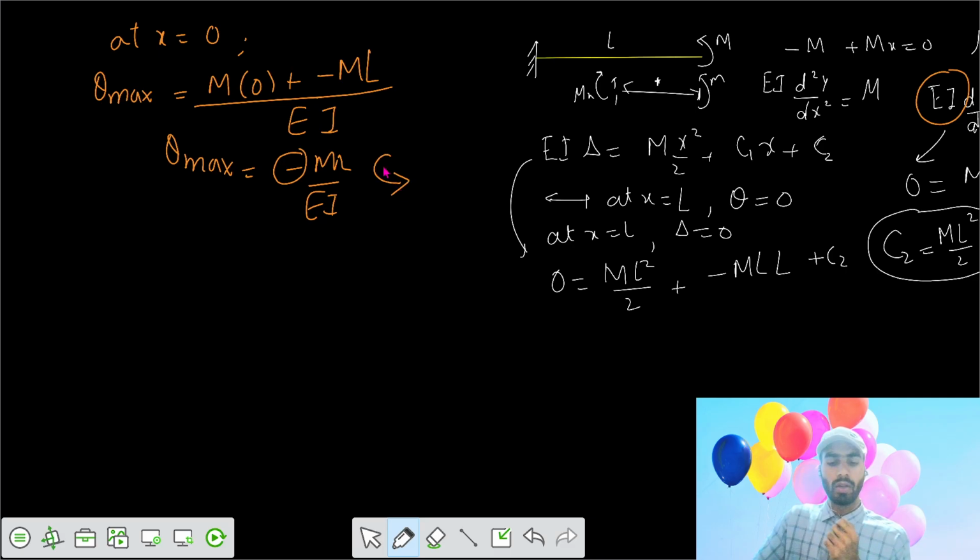So you are applying, say this is your fixed cantilever beam. You are applying an anti-clockwise moment. If you are applying an anti-clockwise moment, the beam would deflect upwards. Accordingly, we have the deflection upwards, and then the theta, the rotation, is also anti-clockwise.